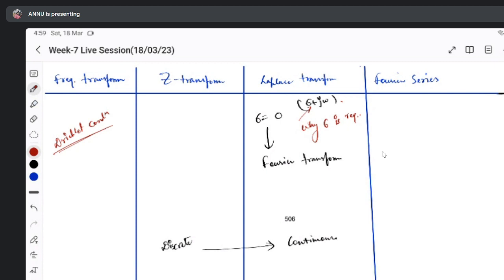But we can have a Laplace transform because the e to the power of minus sigma t pushes it down, so that we can have at least a Laplace transform, if not a Fourier transform. So sigma is required to have the converging response. And the Z transform is just a discrete form of it, and we also call it DTFT if r is equal to 1.